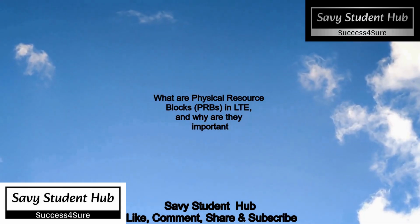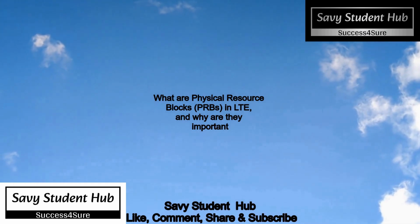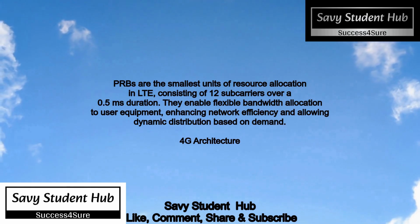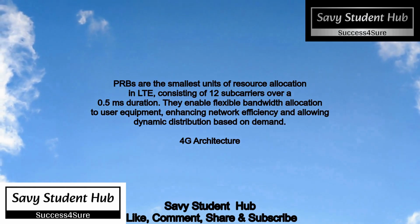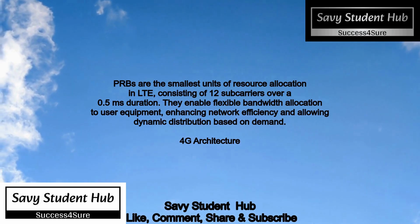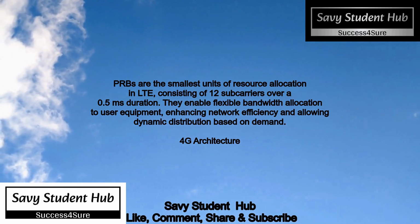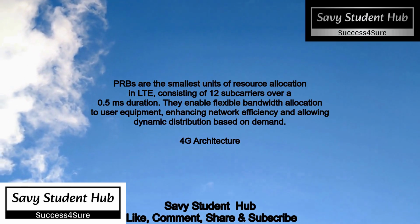What are physical resource blocks, PRBs, in LTE, and why are they important? PRBs are the smallest units of resource allocation in LTE, consisting of 12 subcarriers over a 0.5 millisecond duration. They enable flexible bandwidth allocation to user equipment, enhancing network efficiency and allowing dynamic distribution based on demand.